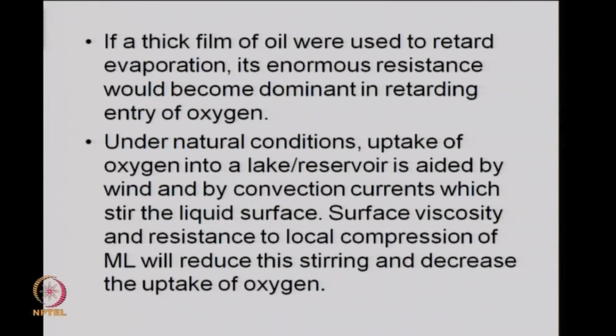But if you have monolayer, then it could retard the stirring also, the convection inside, and besides offering resistance to diffusion of oxygen, it would even decrease the uptake of oxygen. So, we need to be careful here, and those considerations actually lead to a rough realization that we have RL almost doubled, which means the oxygen deficit will be also doubled.